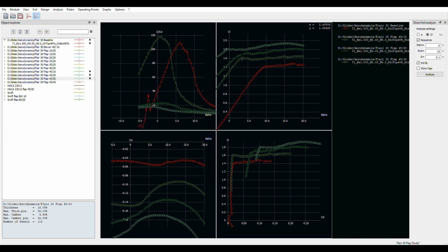So with a hinge point way far forward and the flap representing the majority of the flying surface of the aircraft, and he dumps the flap, loses all his lift. Excuse me, I said that wrong. He dumps the flap and reduces the stall angle of attack down to a very small number, and he just turns the aircraft into a brick.